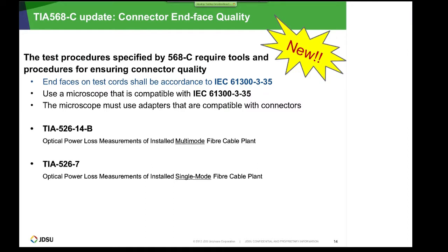What is very important for you if you are using such cables is that a standard microscope is not enough. You should be equipped with an optical microscope which is able to perform pass-fail analysis according to this standard. Otherwise, you are lost, because we are human beings, and for somebody, the surface of the optical interface looks, oh, it's clean. For another person, oh, it is not clean. And this standard strictly eliminates the impact of personal interpretation of whether it is clean or not. The standard even has some chapters or paragraphs defining conditions for multi-mode as well as for single mode. And these conditions are different.